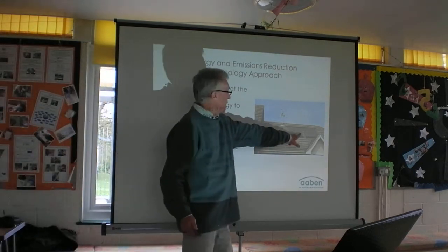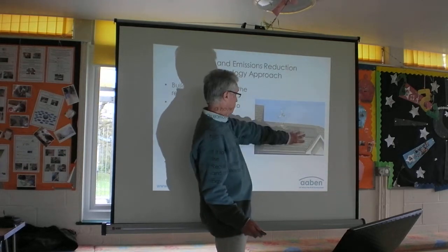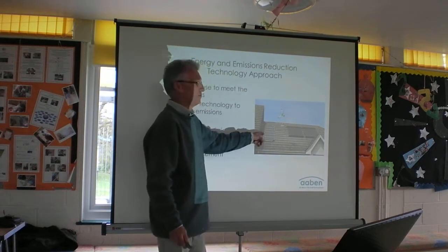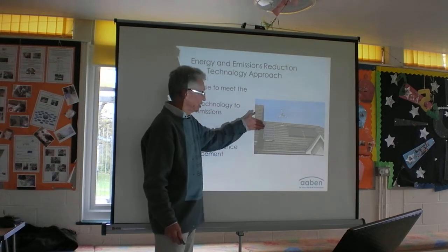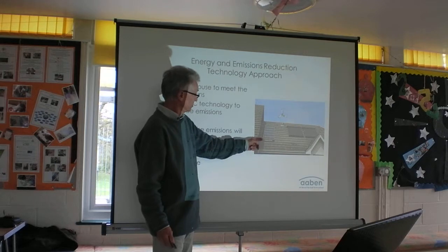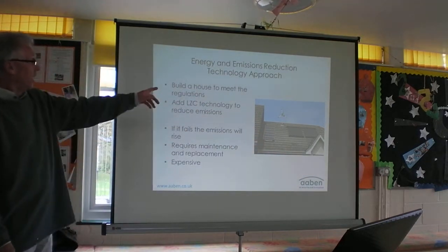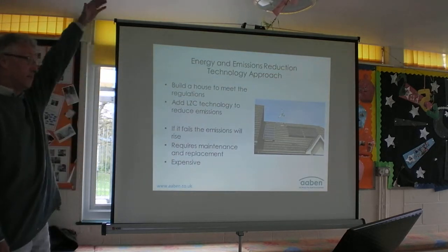Nice solar thermal panels, they will work quite well. They're about the right size for this house, if it's a sort of 3-4 bedroom house, and they look like they're in the sun. A very tiny PV panel, which is too small to power a telly, and it's got a shading bit here. Well, when that panel will not be working, because if you knock out a bit of a panel, the whole string goes down. And I won't even mention the propeller on the roof. You know, you've got to be 10 metres above the roof.